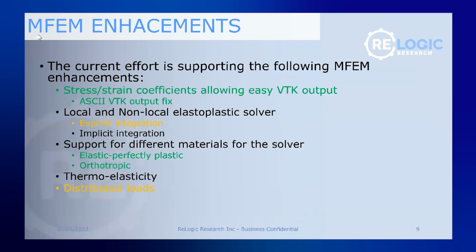So in addition to the software layer bringing in these pre- and post-processor capabilities for MFEM, we are also taking on some MFEM enhancements that hopefully are going to make their way into the next release of the code. We've added the ability to get stress and strain data for VTK output.